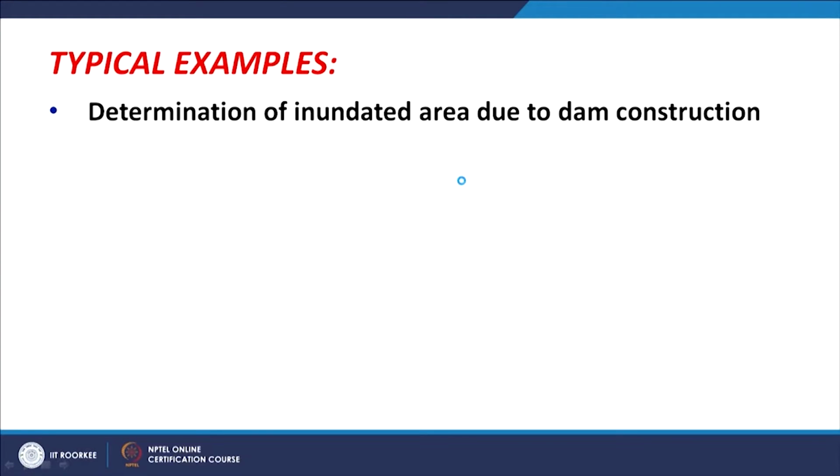This is a very much required analysis, and nowadays, like in India, a lot of small size dams or recharge structures or check dams are created for groundwater recharge. Before really anything happens, we can model not only the location, but the height of that dam, and once it comes on the ground, how it will inundate the area, how much area it will get inundated.